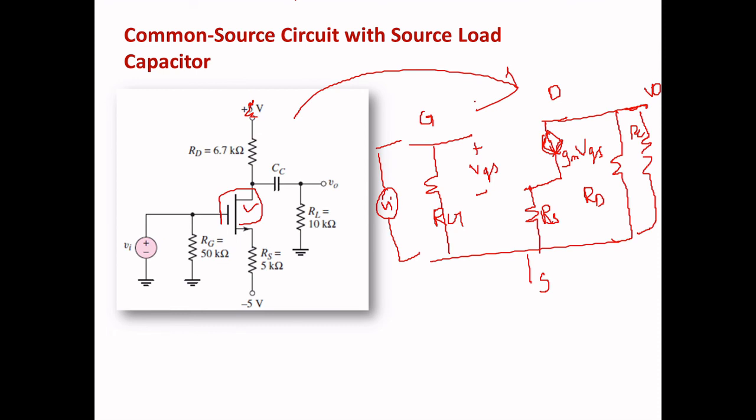Now what we want to derive is your gain, and we want to derive your frequency also. We know the formula for finding your cutoff frequency. This capacitor will work in the lower frequency. The cutoff frequency formula is FL equal to 1 divided by 2 pi tau s. What is the tau s here? Tau s is going to be a product of R into C. Here what is your load resistor?